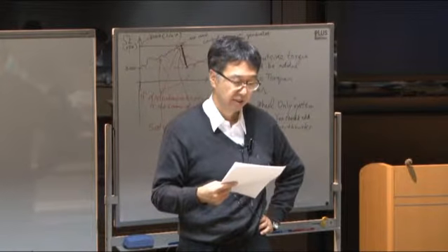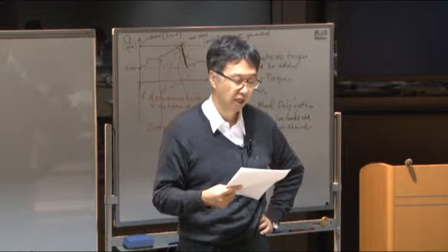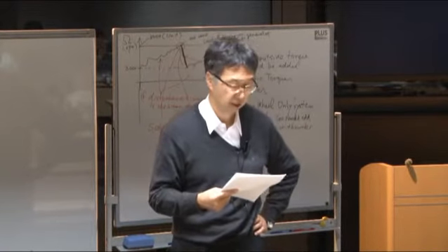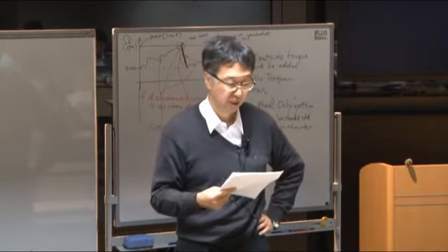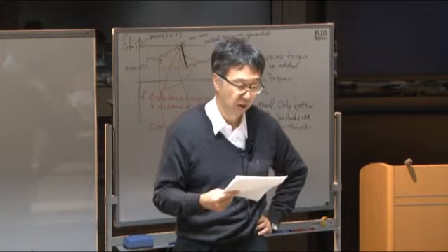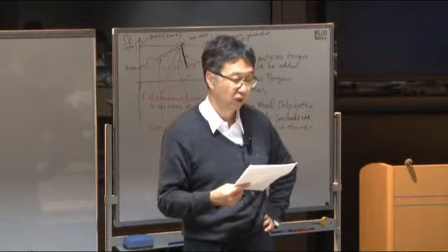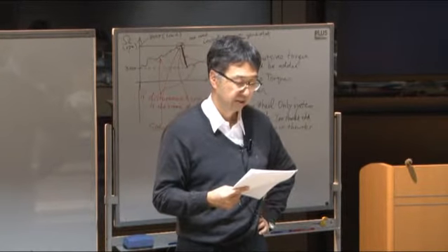Okay, and the fourth column is orientation accuracy, attitude control accuracy, and you have three values: the roll accuracy, the pitch accuracy, and the yaw accuracy. Roll means around the x-axis, pitch means around y, and yaw means around z.